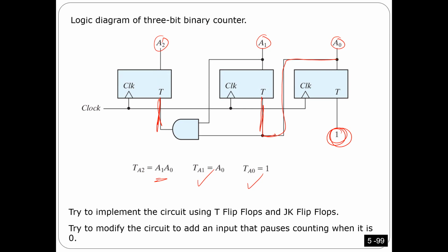But what you explained, I'm going to say it again before I tell you how it is related to counting. Okay, I'm going to tell you, but for now, I'm going to say the observation again. The observation is, I see, the first one here is toggling all the time. Clock comes, toggle. So every clock it toggles. This one is going to only toggle when E0 is 1. This one is going to toggle when E0 and E1 is 1. Okay. This is actually the truth table you are doing. So if you make a truth table, guys, for example, you have here X, Y, Z.